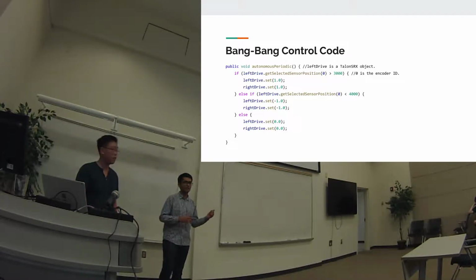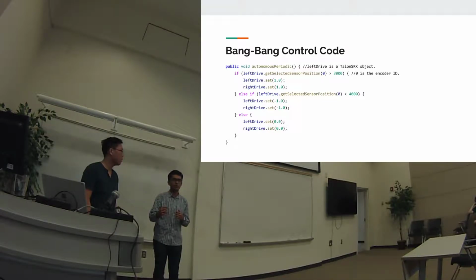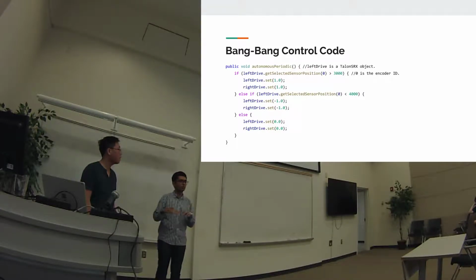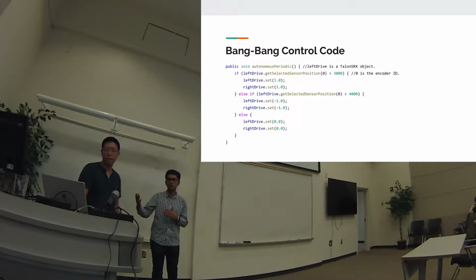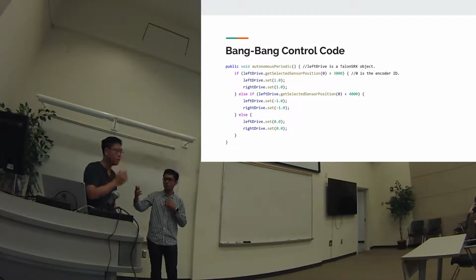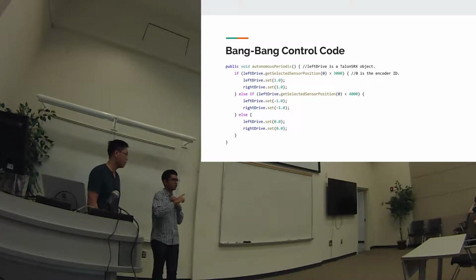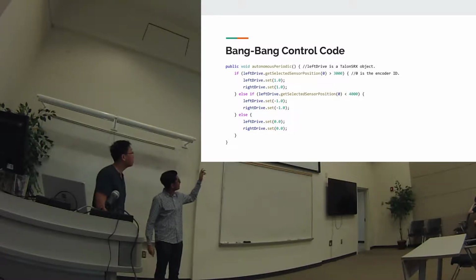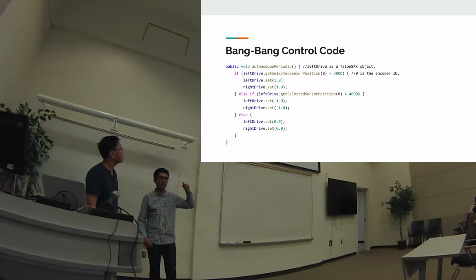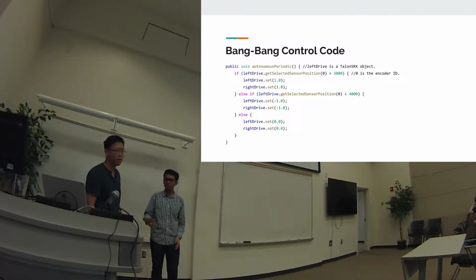That's basically getting the sensor that's wired to the Talon, and through your RoboRio online dashboard or through the code, you can just set it to a certain ID. In this case, it is 0. Also, one thing to remember if you're going to use this code is the symbols for the greater side and left side should actually be switched, because once it goes within that range, it should stop. So it's the other way around.